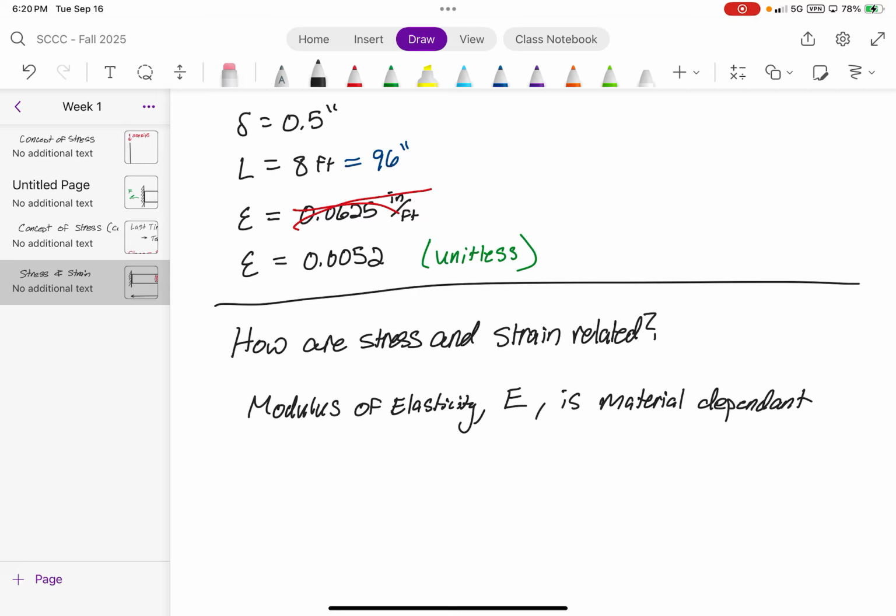If you don't know, look at the table. Well, the steel is. Steel is going to be a lot more stiff if it has the same properties. Now, let's say that the aluminum, you increase the size of the bolts. Now you have the geometric property in play with the stiffness as well as the material property.